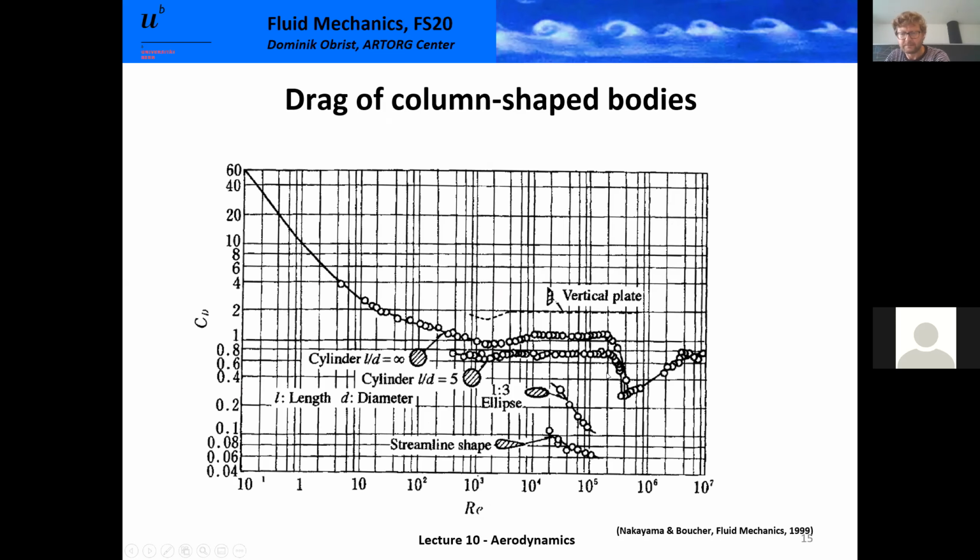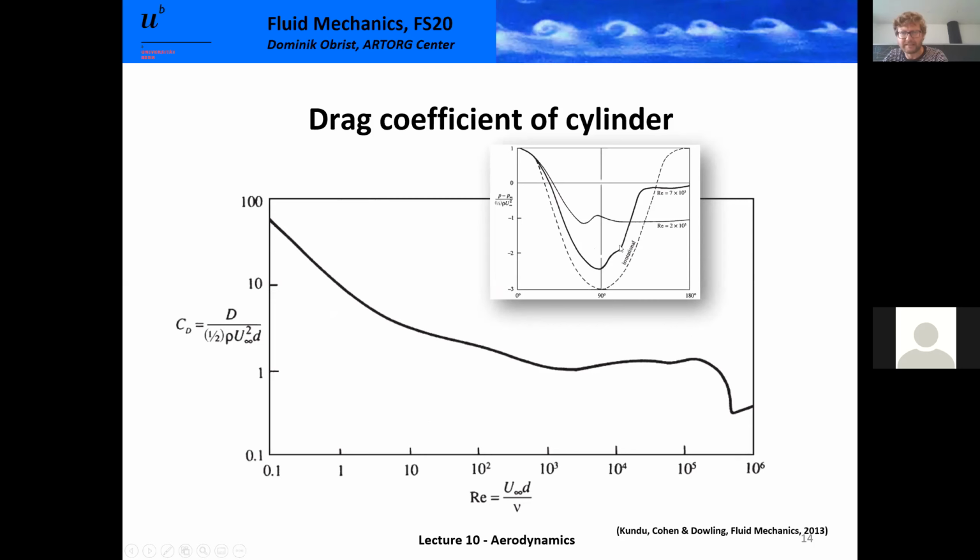And we can now assign the thick solid line, which is the very high Reynolds number case beyond the drag crisis, to this region here. And the thin solid line before the drag crisis is associated with this region here. So this is a drag coefficient of about 1.2. And after this, we have a drag coefficient maybe about 0.4, 0.5.